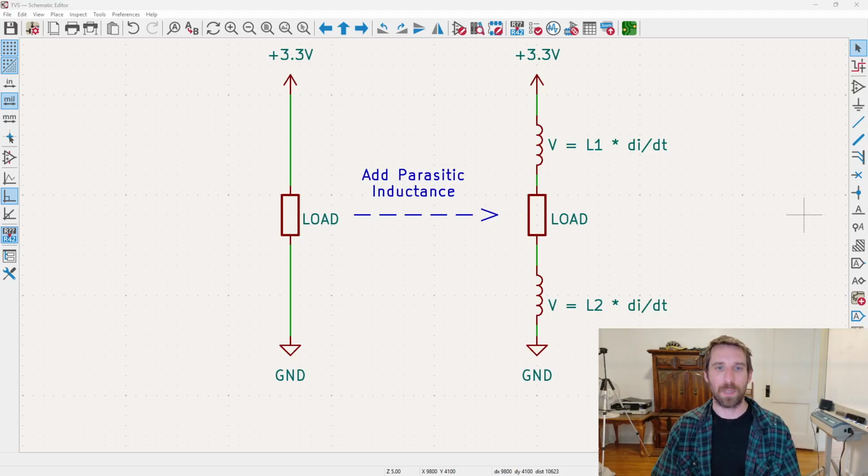Power integrity problems are a good way to make yourself miserable. It is an intermittent problem always. The problem reported can be really weird and hence really difficult to track down, and it's almost guaranteed to involve a layout change, which we don't want to do because the board's probably already in production, because it's so intermittent that it was never caught during the prototype stage. So to avoid all that mess, we're going to talk about in this video what to do.